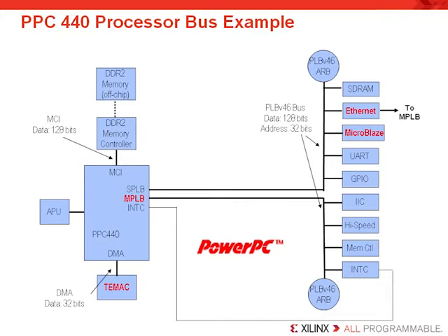Note that the Ethernet controller should be drawn to attach to both the master PLB and the slave PLB because sometimes it's a slave component and needs to communicate on that bus. This would be the same with a PCI core. In fact, if you built a similar system with a base system builder, you'd have the ability to add these components and attach them to the buses the way you'd want.